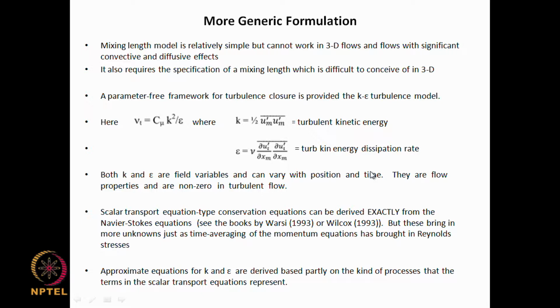Now, one other feature of turbulent flow is the energy cascade, where turbulence is generated at some eddy size characteristic of the instability mechanisms in the major, strongly shear regions of the mean flow, and that energy is cascaded down into smaller and smaller eddies, and finally it is converted into heat, dissipated.